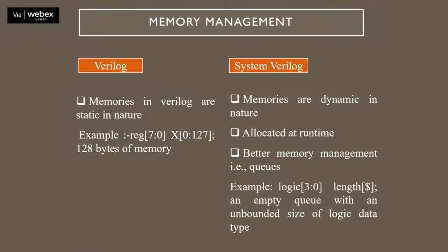The dynamic kind of arrays we define are not synthesizable. Only the fixed size arrays, and any operation done using them, are synthesizable. Whereas dynamic array allocation, addition, deletion, or any operation done on them, are usually not synthesizable.